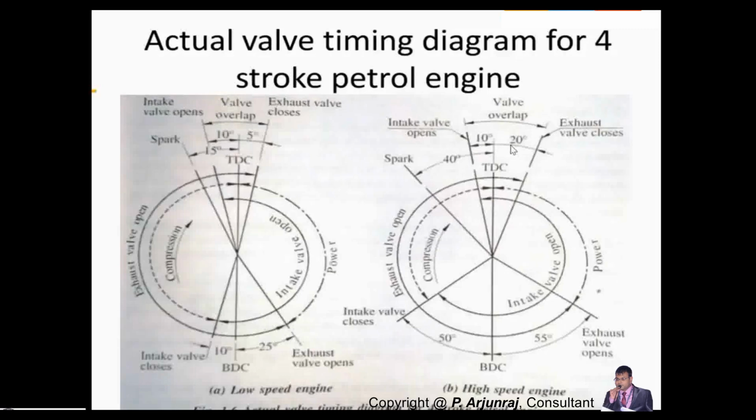In the case of the high speed gasoline engine, the inlet valve opens 10 degree before top dead center, and the inlet valve closes 50 degree after bottom dead center.